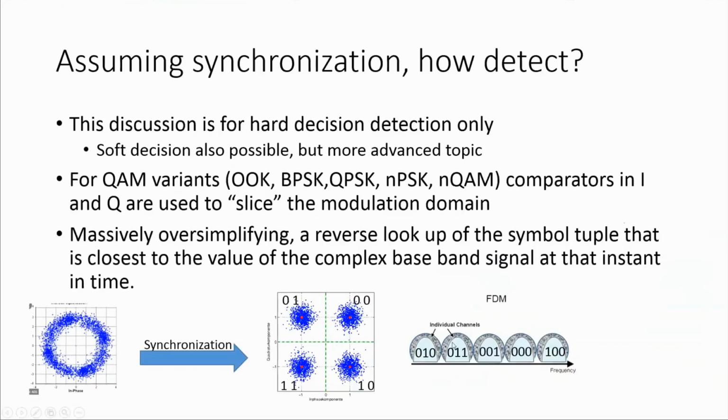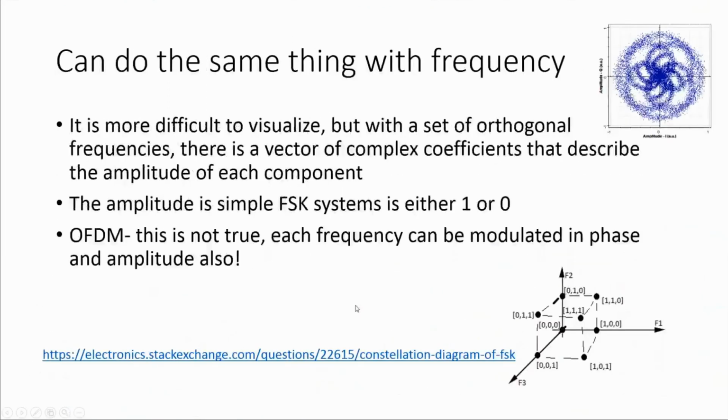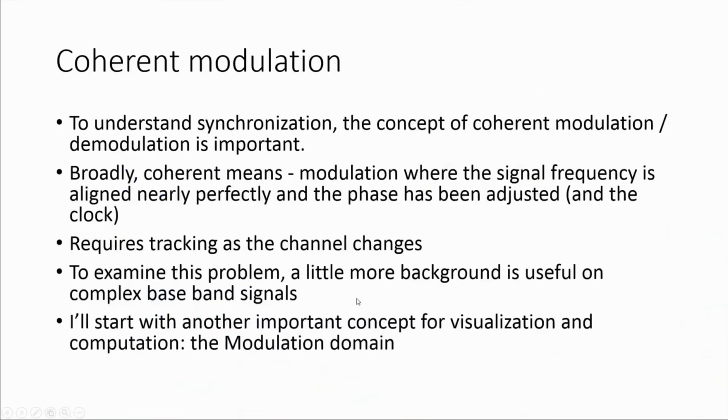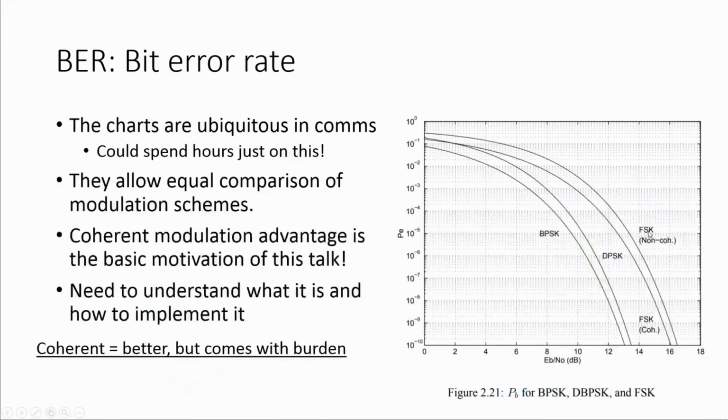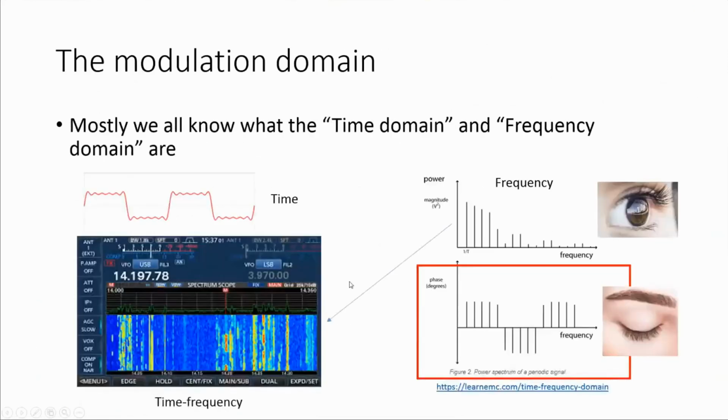In the frequency domain, it looks a little different, because phase isn't important. You can do FSK without knowing phase. There's some trade-offs, and we saw those earlier. Let's see if I can find it. Backwards, here we go. If I have FSK versus coherent modulation, my error rate is significantly worse. And that's what we pay. We say, okay, we're not going to phase synchronize, but this error rate's much higher. And we still have to know the frequency, though.